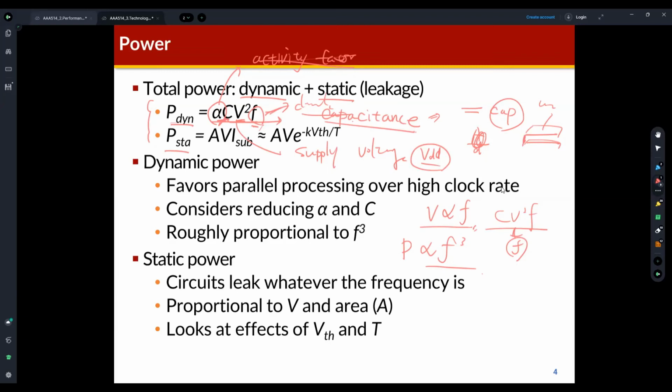It is related to running cost, manufacturing cost, thermal, and many other costs. Since P is proportional to the cube of the clock frequency, if we consider the power consumption of the processor, it's not good to increase the clock frequency.